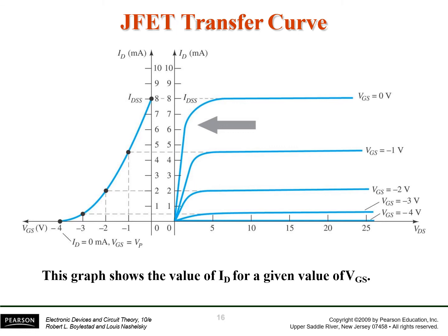As we further increase the negative potential between G and S, the gate and the source, up to minus 2 volts, the current through the drain, ID, saturates at 2 milliamperes.